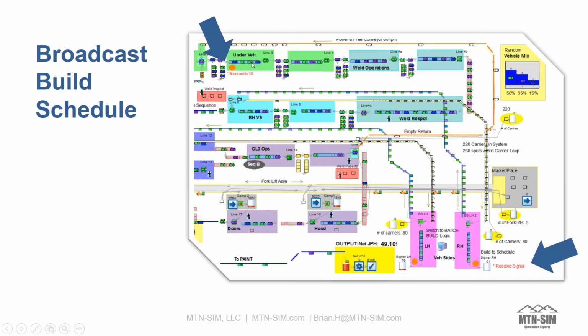And when we multiply all these availabilities together to get an overall availability for a line, we can see that it doesn't take long before the overall availability becomes a potential issue. This is where we break up some of the synchronous behavior through decouplers or buffers. They could be anywhere from 2 to 8 units, and that might be sufficient to break up some of the synchronous downtime behavior.